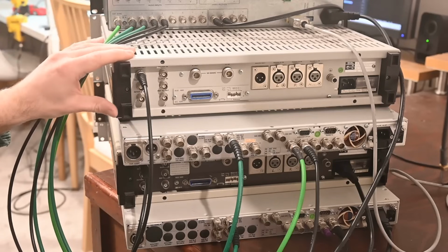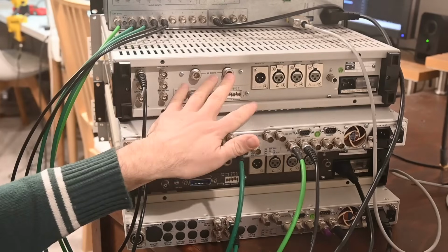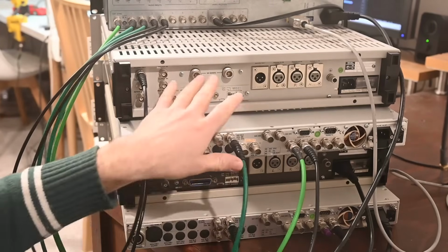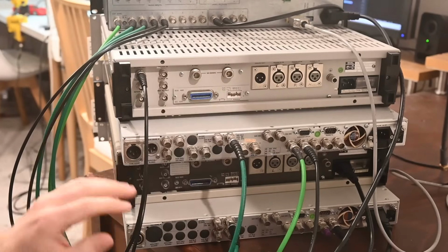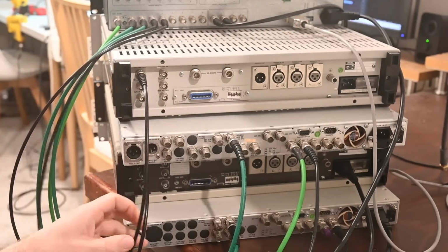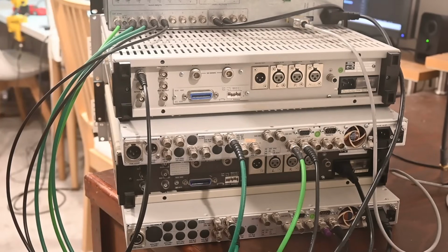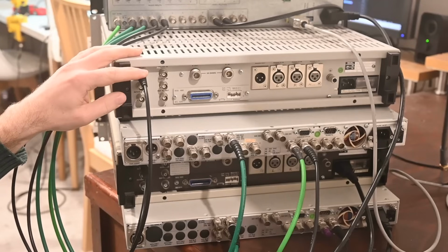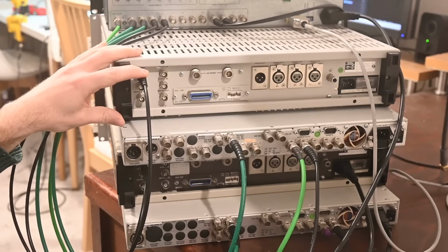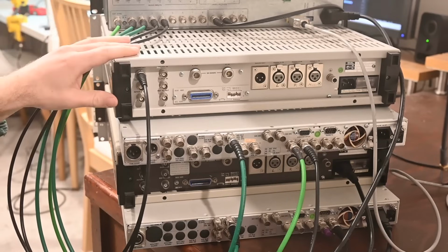Additionally, we have our two NICAM coders here, and these units actually do have RF modulators built in of differing standards, but we're not actually using that functionality at all today. What we're doing is taking the baseband digital outputs and feeding these straight into the video matrix switch. Now, you might be thinking, what the heck? Well, this interface here happens to be electrically compatible with composite video, and we can actually quite easily switch it inside a matrix switcher like this one.